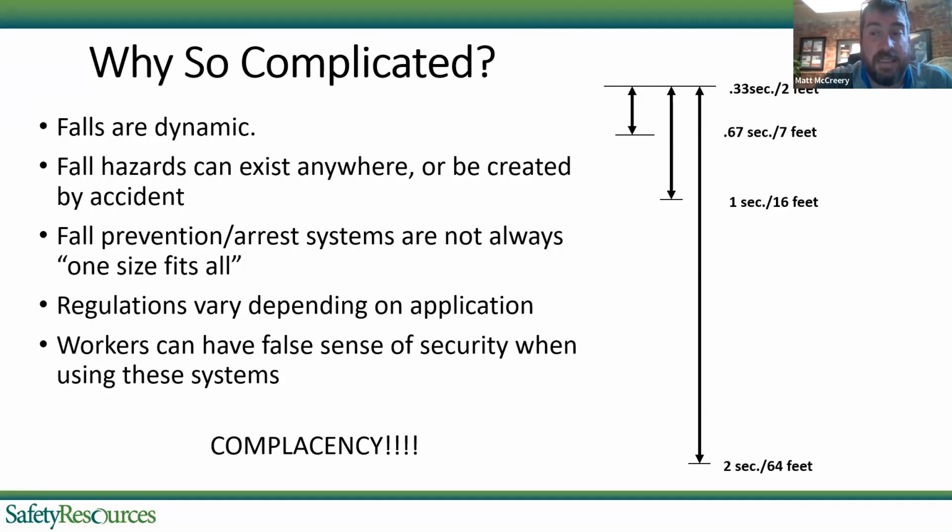And is that policy written in a way that meets what OSHA tries to establish as a first man up rule, meaning the first man up, I believe, is able to go and set that very first peak anchor, tie off to it, and then set the rest of the peak anchors for the crew. And then from there, that's how you would maintain 100% fall protection. But that first guy up would not be tied off while he's setting that very first anchor.